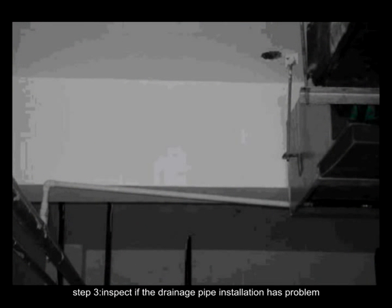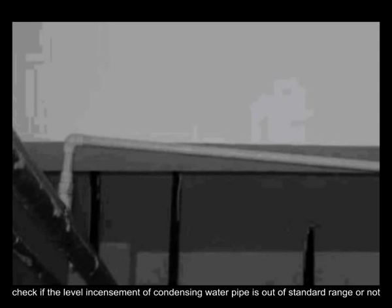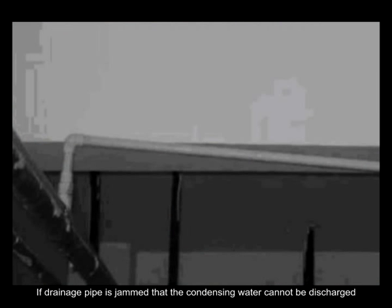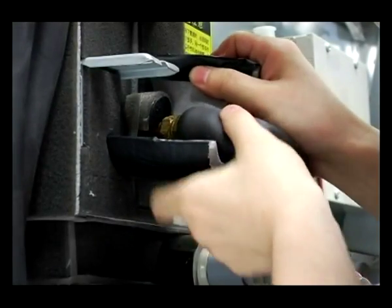Step 3. Inspect if there is a problem with the drainage pipe installation. Check if the level and insulation of the condensing water pipe are out of the standard range or not. If the draining pipe is jammed, the condensing water cannot be discharged. Check if the lean degree is bigger than 1%, and if the pipe connector and throttle part are well heat insulated.